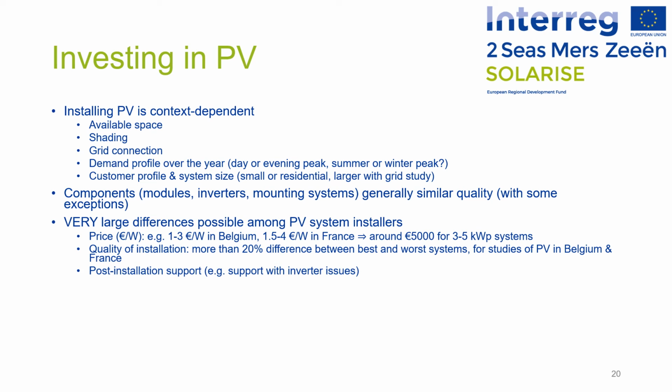The other issue is the quality of installation, as studies have demonstrated that more than 20% difference in energy yield can be seen between the best and the worst systems in Belgium and in France, and also the quality of the post-installation support. For example, if an inverter sees issues, how responsive is the installer to help sort those issues?